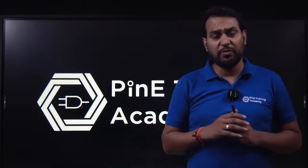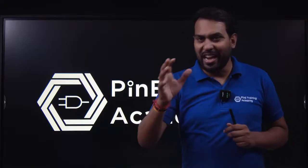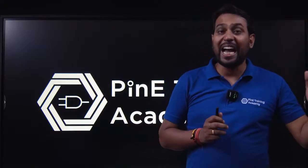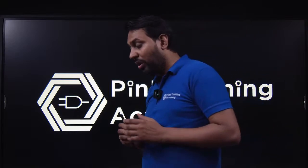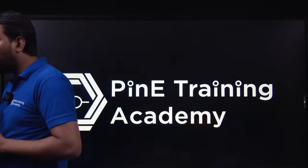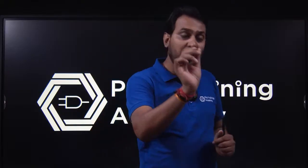After the layout design, you go for physical verification, that is the Pegasus verification system. In the Pegasus verification system, we have DRC and LVS. DRC represents design rule check, and LVS represents layout versus schematic. In DRC, every tech node provides the DRM, the design rule manual, which has a set of rules. For example, you should have a minimum spacing of something. Everything is given, so you design the layout on the basis of the DRC.